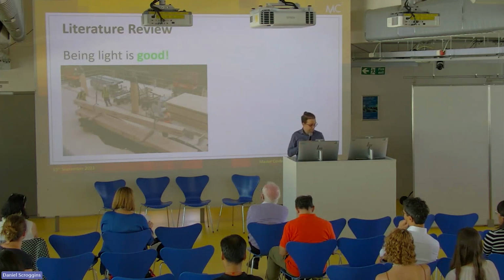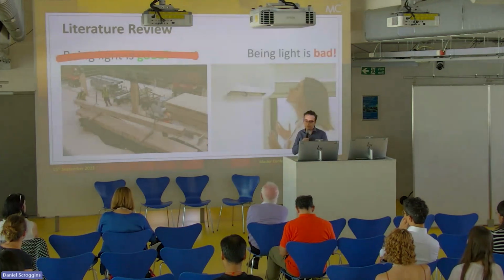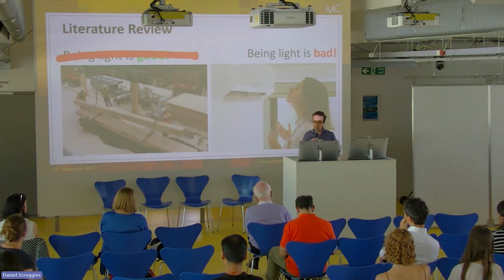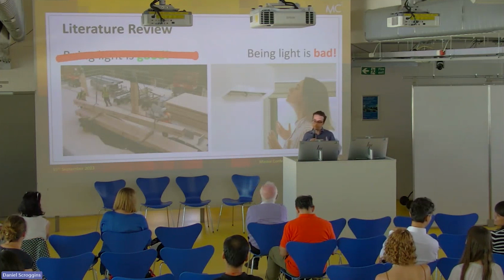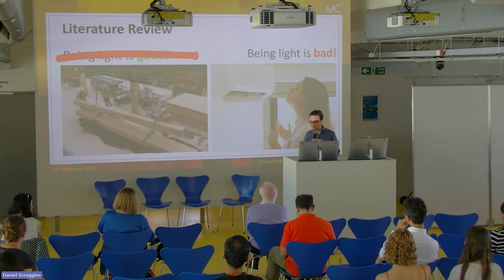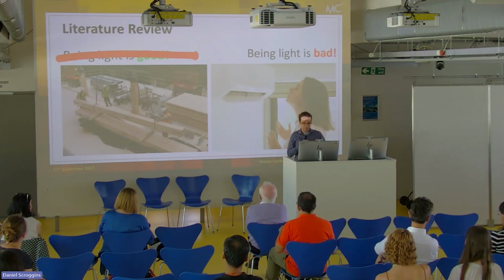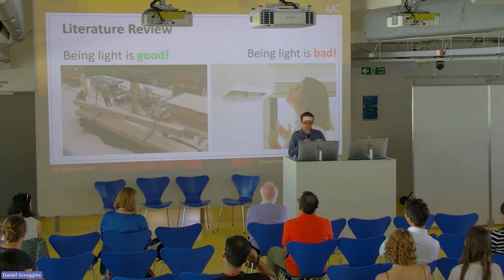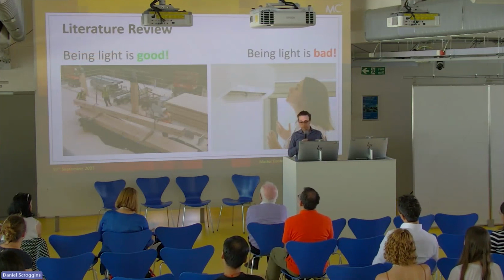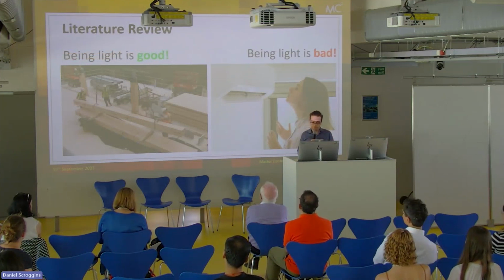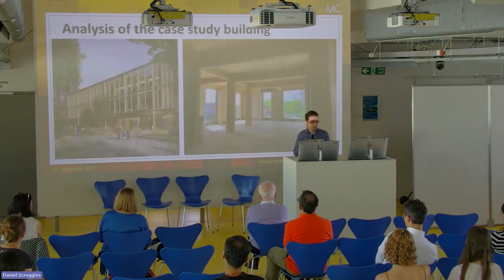But on the other hand, mass timber walls and slab translate to a much lower thermal mass capacity, making the building require more energy for heating and cooling than if it was made with heavier materials, and leading therefore more easily to overheating scenarios, which is quite a problem considering the climate heating situation we're in. But the embodied carbon savings are usually so high that on a whole life cycle perspective, it still makes sense to use mass timber. So this is my case study building.